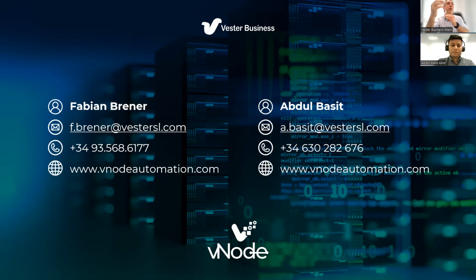Now, this is one store and forward. There is another store and forward, which is what happens if the vNode in IT, which is connected using MQTT to the cloud, loses this connection? Because that can happen. Let's imagine you just lose internet in your office for like 1 hour. What happens? So I'm losing the data? No, you're not losing anything. That vNode will keep collecting data from the control networks, the real-time data, and will keep the data in the hard drive.